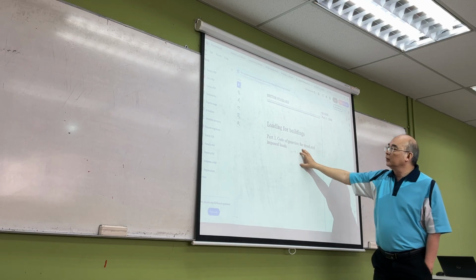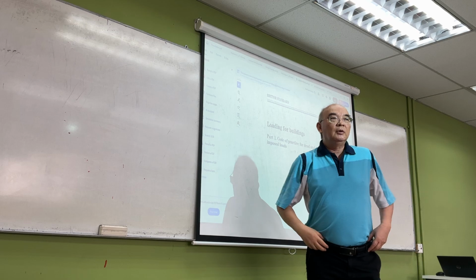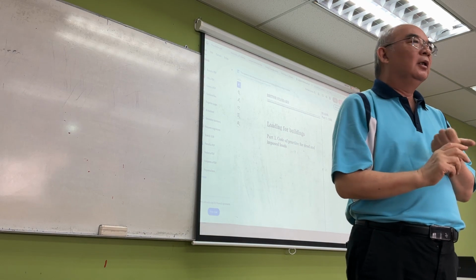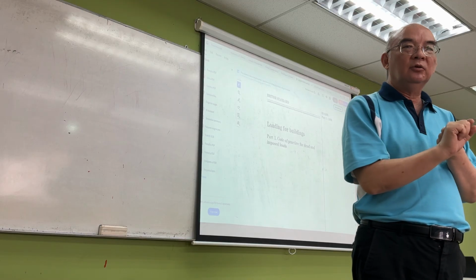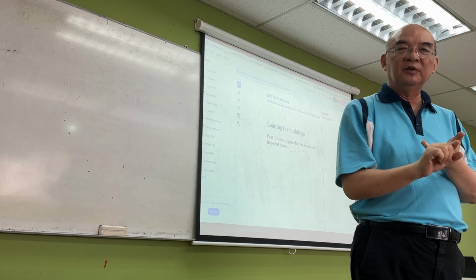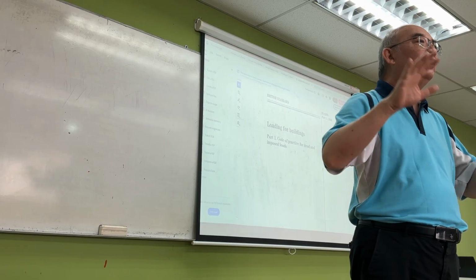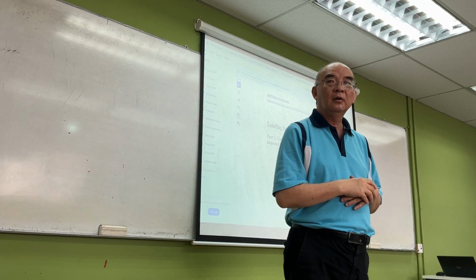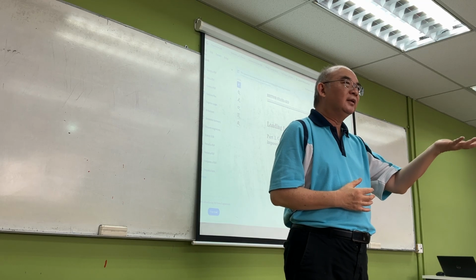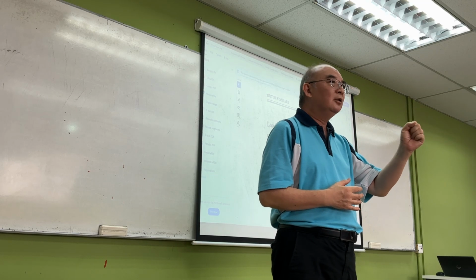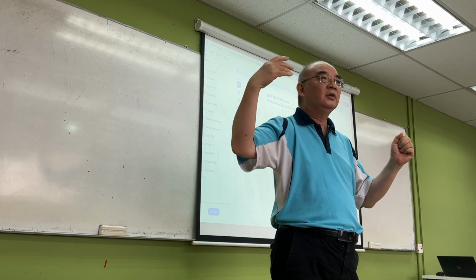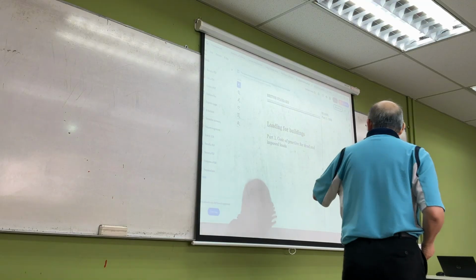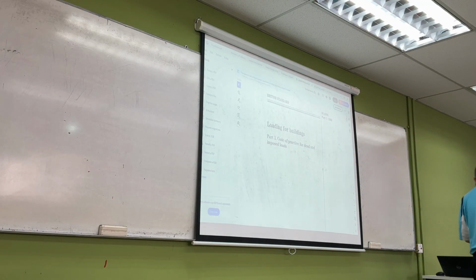So in this Part 1, you learn, for example, what kind of loading a hospital floor should be designed for, what kind of loading a parking space should be designed for, and what kind of loading sports facilities should be designed for. Because different usage will have different design loading. For example, a residential area has a lighter loading than a stadium, because a stadium is more crowded and packed, right? So this is given in Part 1.